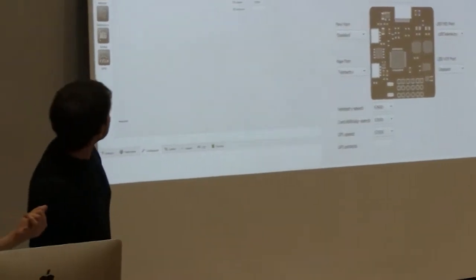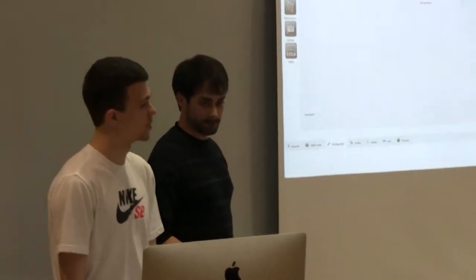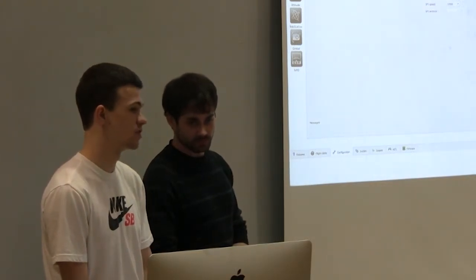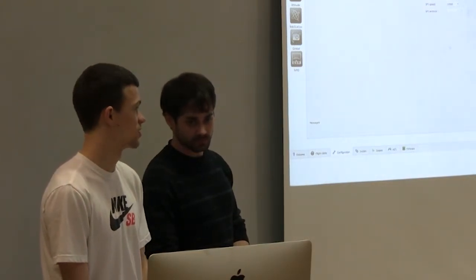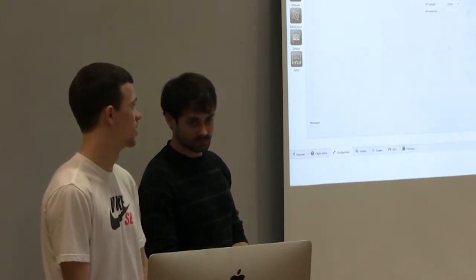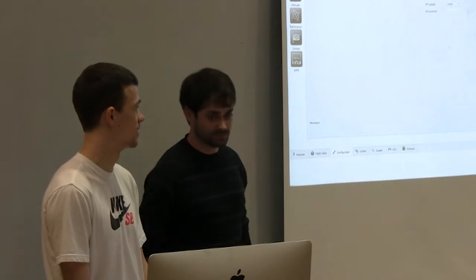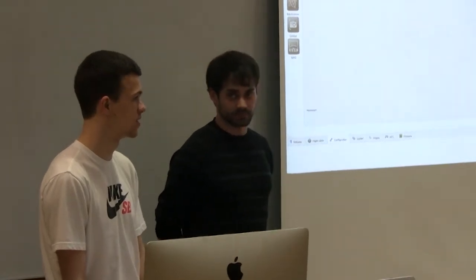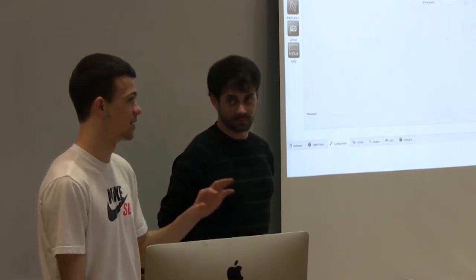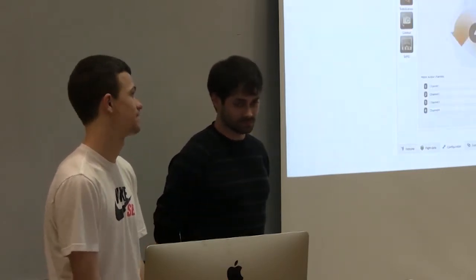That's an important number to remember if you're having trouble connecting your ground control to your flight controller. The first thing to check is whether your baud rate is correct, because some defaults will be about 9,600 or upwards of 115,000. And if it's off, it might not connect.